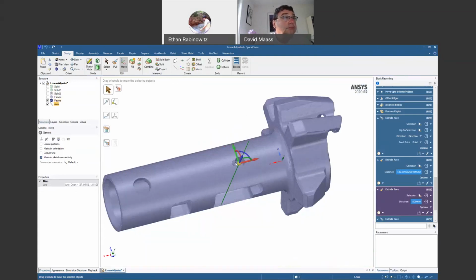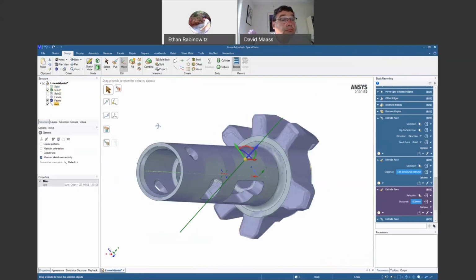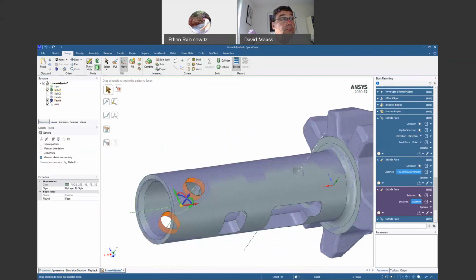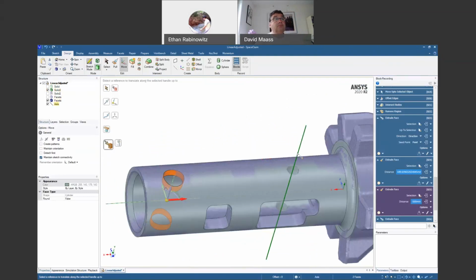In doing that, it'll give us that location. If I fit a cylinder there, we might still need to make some adjustments, but because I know that we've already made the adjustments here, what I could do is take these with our move tool in this direction, and do an up to, and if I just hold control while I go up to this axis, it'll only copy them in this direction. So there should be no movement in any other direction. And then once those are made, I could just resize them to the smaller hole size.